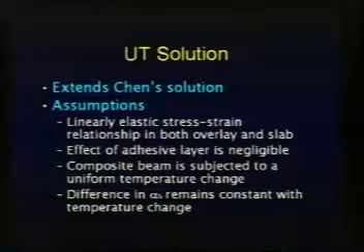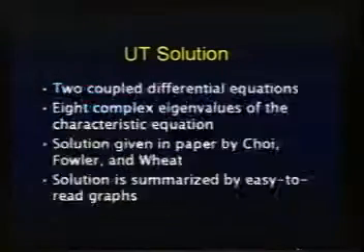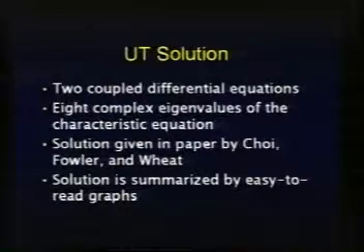We neglected that adhesive layer between the overlay and the concrete slab. But we did assume that the composite beam is subjected to a uniform temperature change, which isn't quite right. We assumed that both the overlay and the concrete are at the same temperature. And we assume that the difference in the coefficient of thermal expansions tend to remain pretty constant throughout the temperature change. That isn't always quite correct.